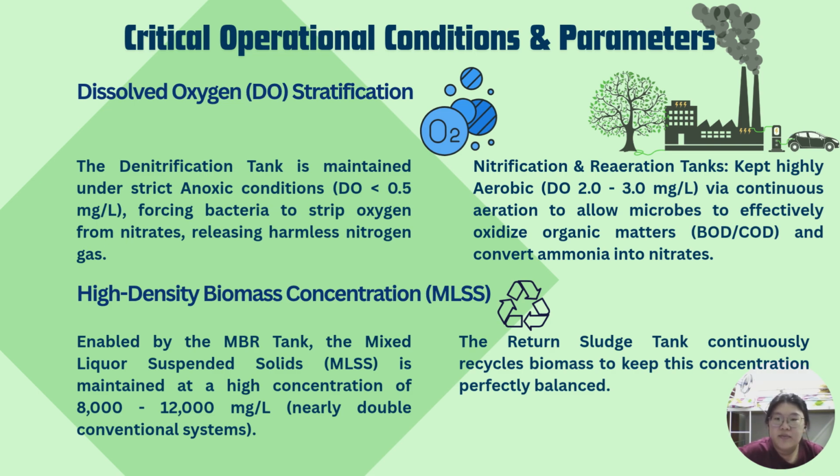Secondly, we monitor the high-density biomass concentration, which is the MLSS, enabled by the MBR tank. The mixed liquor suspended solids is maintained at a very high concentration of 8,000 to 12,000 mg per liter, which is nearly double that of a conventional system, while the return sludge tank continuously recycles the biomass to keep the concentration perfectly balanced.